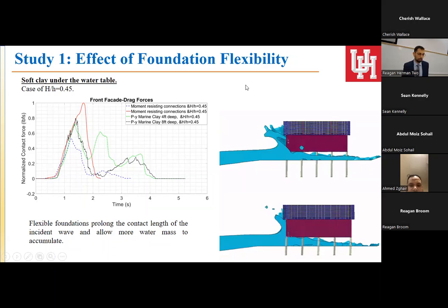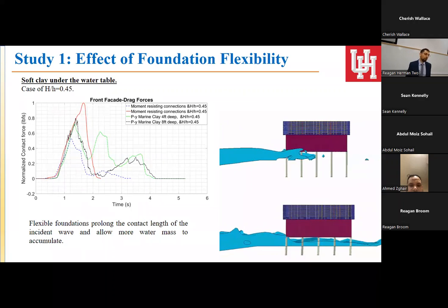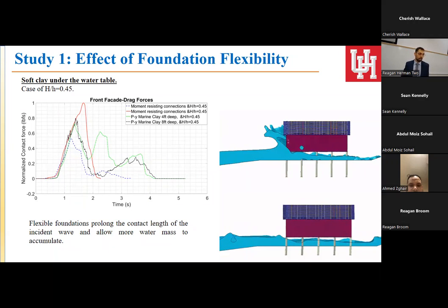Of course, as you'd expect, as you drive the piles deeper, you won't get that much plastic deformation because you basically have more resistance, more soil resistance activated. And this way, the forces still remain the same, but you don't have the consecutive peaks phenomenon.